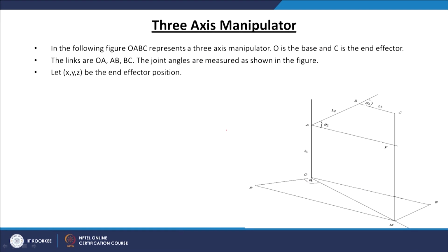If you have a 3 link manipulator, the first link will rotate with respect to the axis which is a vertical line, the second link will rotate about an axis perpendicular to the paper at a particular configuration. It has the axis of rotation parallel to the previous axis of rotation. So, there are 3 axes of rotation, and when the end effector is to reach a point x y z, how do we write the relation between x y z and the 3 angles theta 1, theta 2 and theta 3?